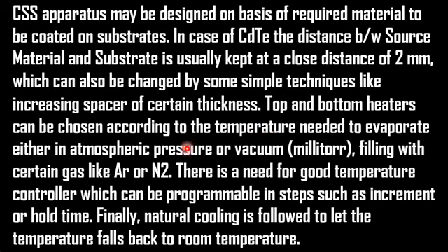Another interesting factor is that in closed space sublimation, the top and bottom heaters can be chosen according to the temperature needed to evaporate, either in atmospheric pressure or in vacuum filled with certain gas like argon and nitrogen. Okay, so basically heaters in the closed space sublimation process are used in low vapor pressure environments, and they may also be used at atmospheric pressure. So please keep this in mind.